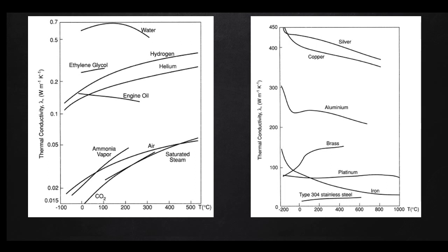W, which stands for watt, is joule per second, and so the thermal conductivity actually dictates the rate at which heat is transferred. So remember what I said before, even though we've got a temperature gradient and we require this for heat transfer to take place, we also need the thermal conductivity to know what rate, or how quickly, this heat will be transferred due to this temperature gradient.